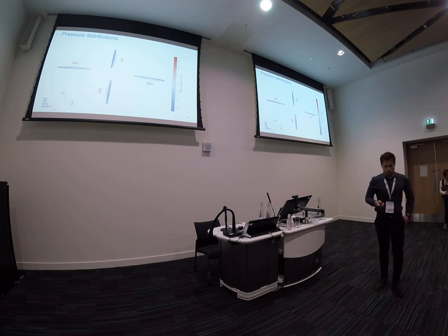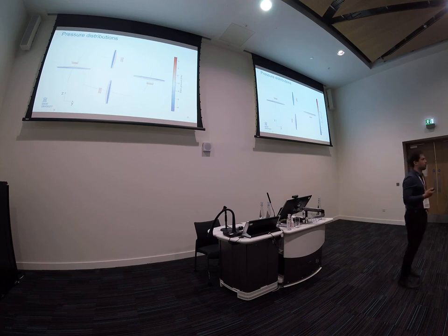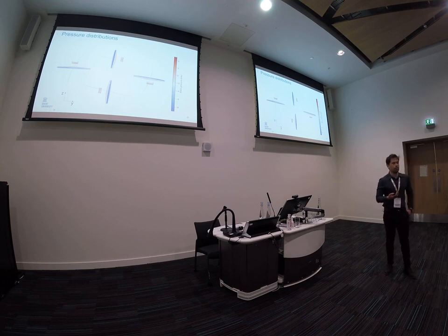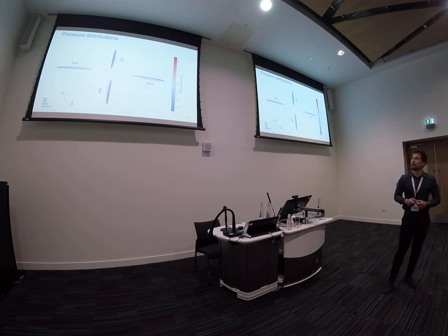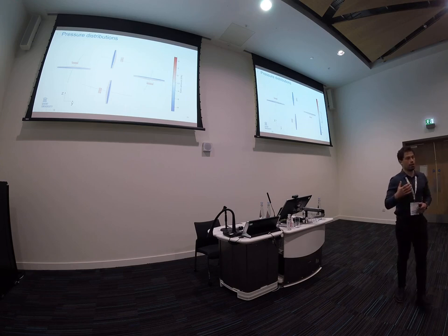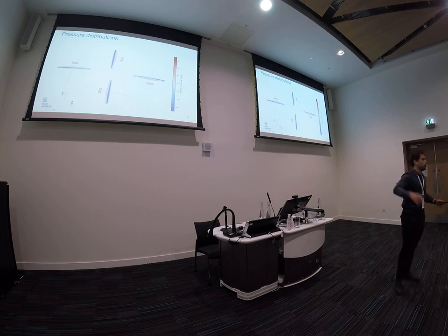Then, of course, these CFD models are quite computationally expensive, but we also get a lot of data from them, which you can use for both quantitative and qualitative analysis. I plotted here the pressure distribution on the full aircraft for 4 positions in the loop, in a direction which is perpendicular to the wind, so in the x direction. You see here that during flight we have varying pressure distributions. Also, you can see the asymmetric distribution. You have some more pressure here due to this rotational motion.